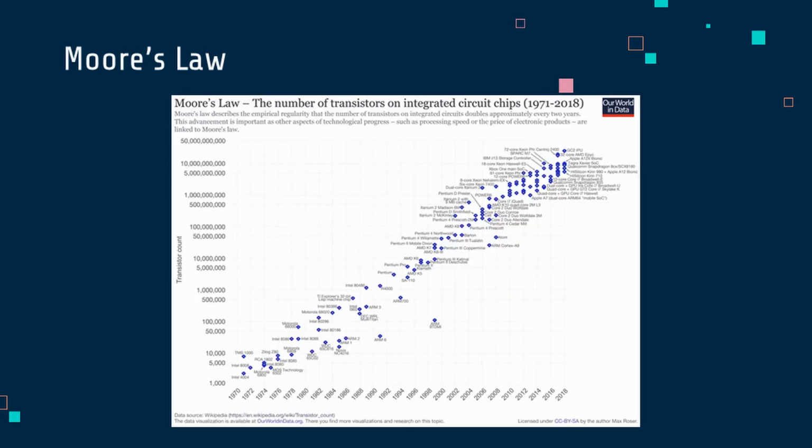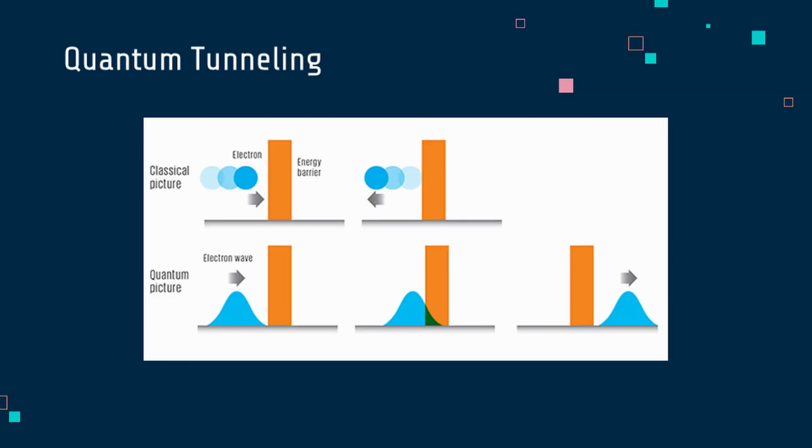Moore's Law is a theory that claims that the number of transistors on a circuit chip doubles every 2 years. It has been relatively accurate as depicted in the graph until recently, as their size, which is in the nanometer range, is beginning to create problems such as quantum tunneling. As the barrier distances are steadily decreasing in order to make transistors smaller, they aren't always thick enough to block current. Electrons can disperse across barriers at finite probabilities, which is what is known as quantum tunneling. This is a major obstacle for chip makers, as it creates a limit for how powerful modern chips can get.